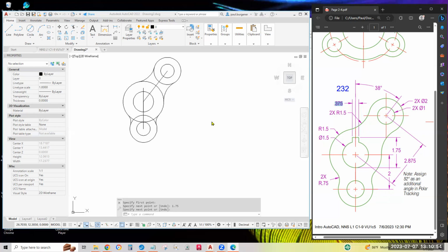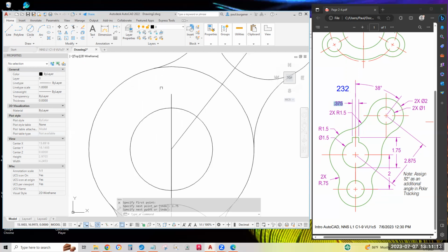We'll draw a line from this top point each direction at 3/16 of an inch. Well, fortunately, AutoCAD understands when we type 3/16, so we don't have to pull the calculator out and learn what half of 3/8 is. We'll draw a line, we'll snap at the top of the guideline and send the line directly to the right, 3/16, enter. Enter to finish.